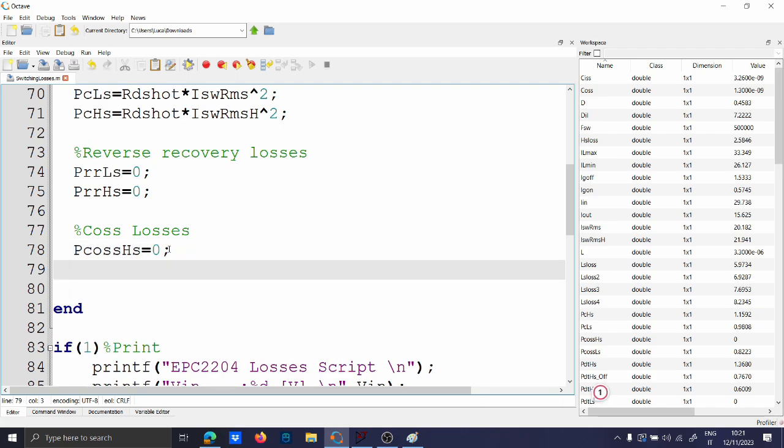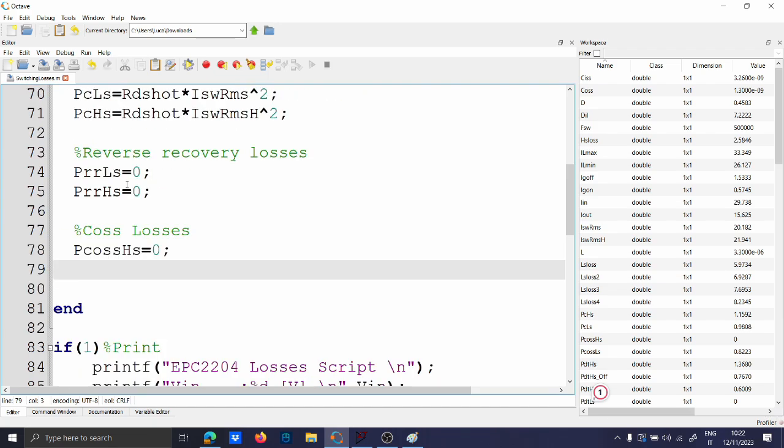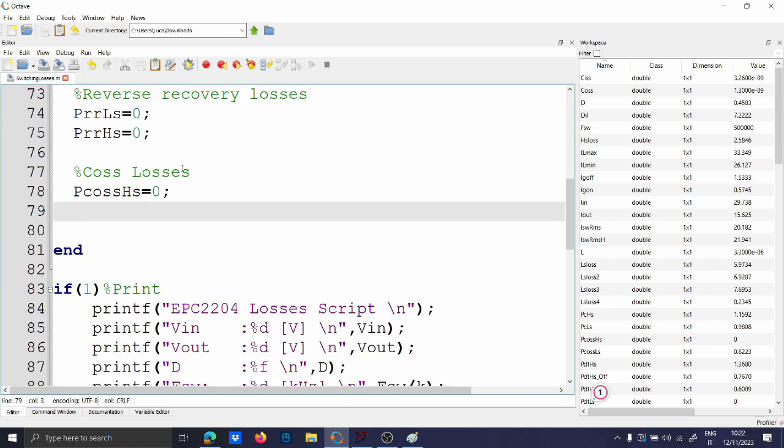Now, I will probably get killed by the physicists, or by the mathematicians, but really, let's discuss this in the comments. I think that you shouldn't consider so much the switching losses of the high side. I think they are negligible in comparison with the conduction losses. You didn't calculate the high side losses. You are a very bad YouTuber. You can if you want, but honestly, you will see that it is not very relevant.